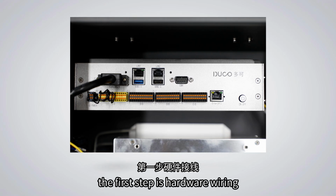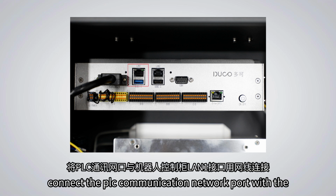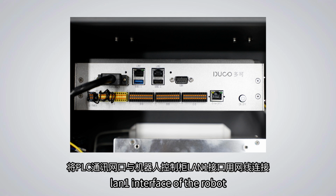The first step is hardware wiring. Connect the PLC communication network port with the LAN 1 interface of the robot control cabinet with a network cable.